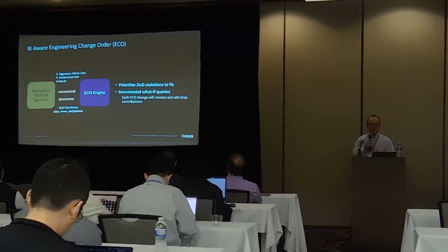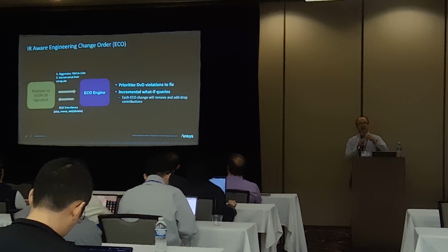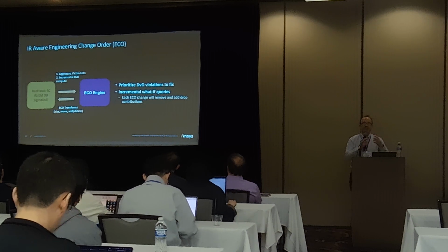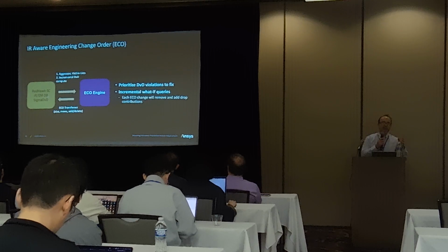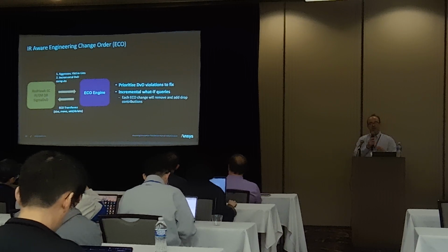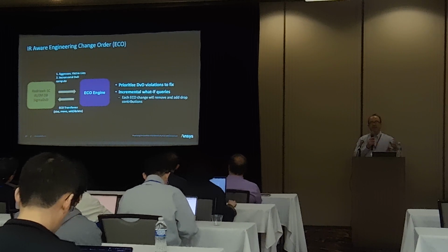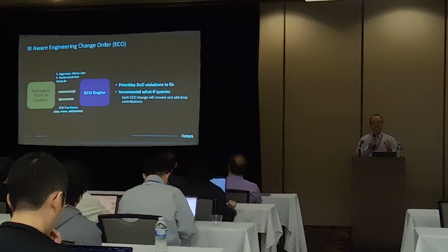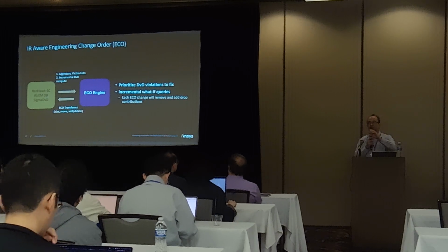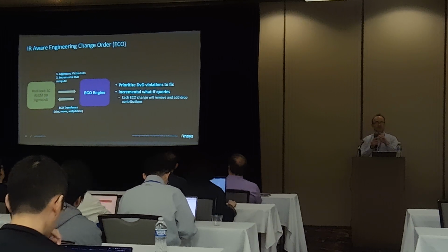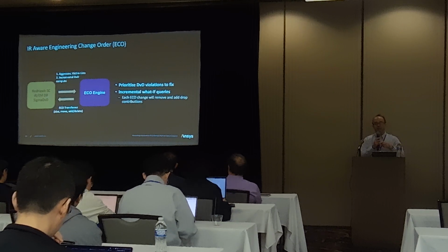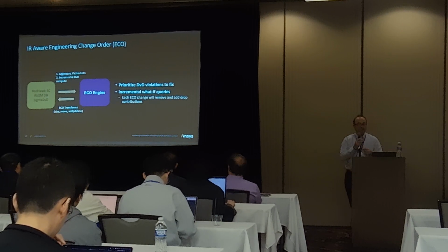Let's say I want to fix an IR problem or a timing problem, make something better. I want to move a design, or resize a gate. These things may change the current profiles, but based on the knowledge and analytics we have from the power network, we can say what the delta voltage drop impact is going to be, a quantified number, so we give them the information to make the right decision whether to commit that change or not.